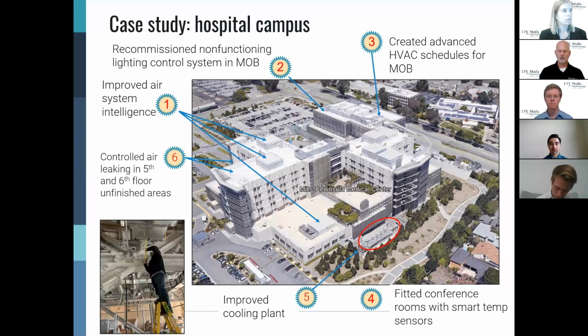So again, we were focused in the first effort on their cooling plant. Again, it's probably beyond the scope of this discussion, but we really holistically re-looked at the overall intelligence behind the plant, and we rewrote and reworked the entire way that the plant was working. It took some enabling technology, some drives that were put in on the primary pumps for the chillers, but a lot of it was just programming and sensors and leveraging what was there.